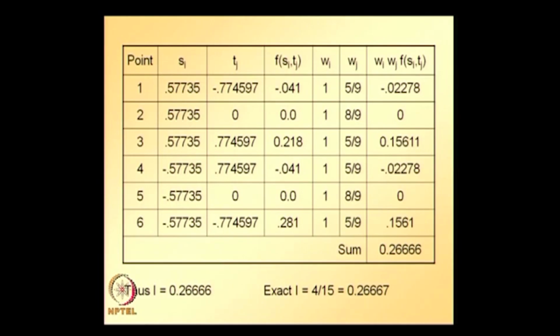So, as a part of this isoparametric quadrilateral element, we have seen how to derive shape functions for 4 to 9 node quadrilateral elements, and we also looked at the isoparametric mapping concept for 2 dimensional elements, and numerical integration for evaluating integrals over 2 dimensional domains. So, now we are ready to develop element equations by taking any one of the quadrilateral elements.